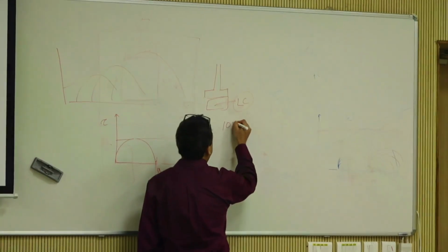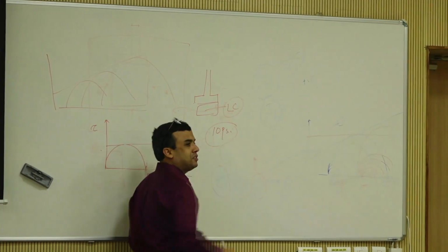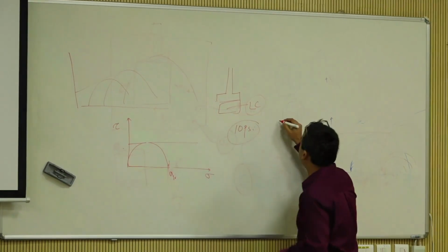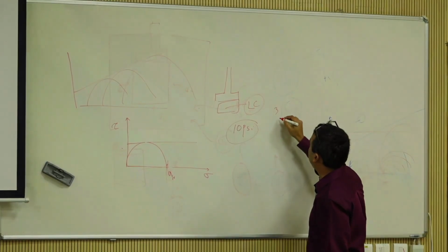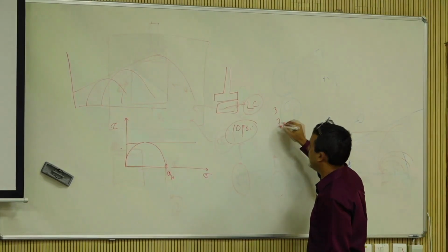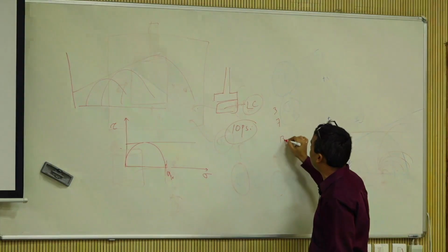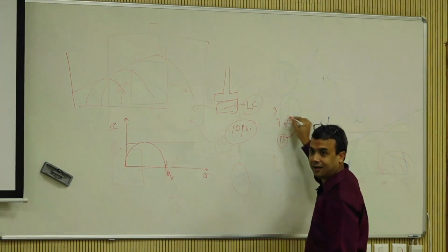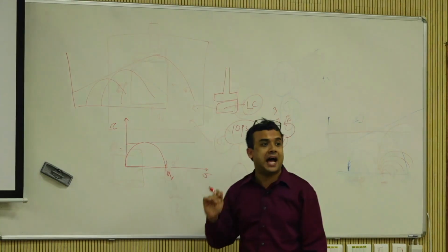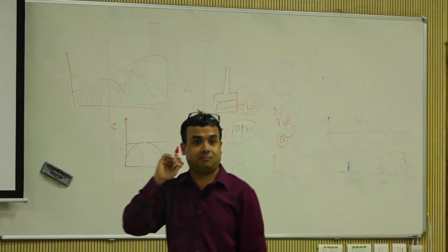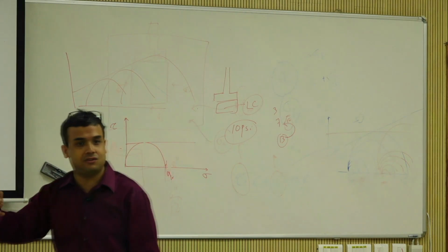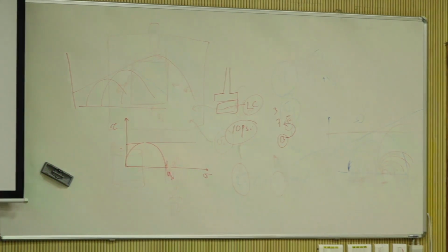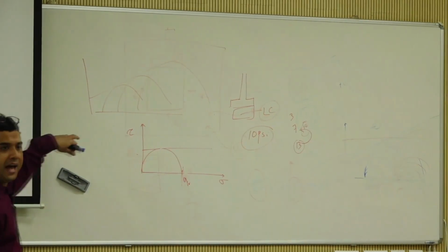When my target stress is 10 psi, the load cell, or the pressure cell, keeps measuring it, saying, no, I'm at 3, go up. So then you go up to 7, like no, still keep going up. Then you go to 13, it's like no, too much, go back, 10. This keeps happening 1,000 times per second, at a very, very fast rate.